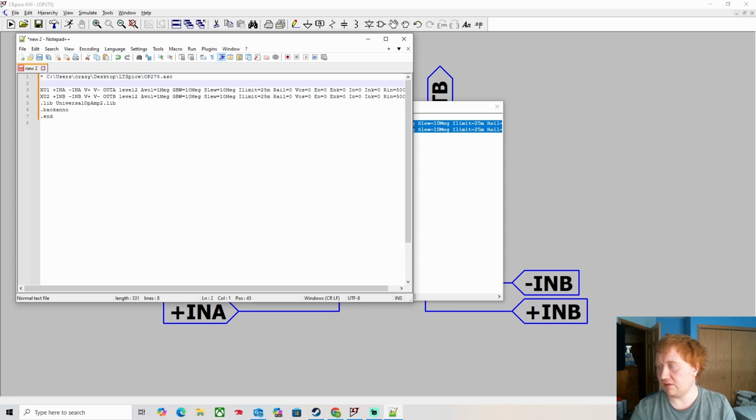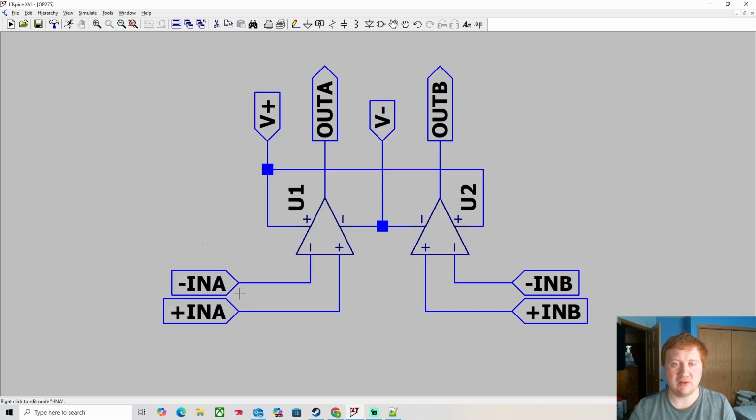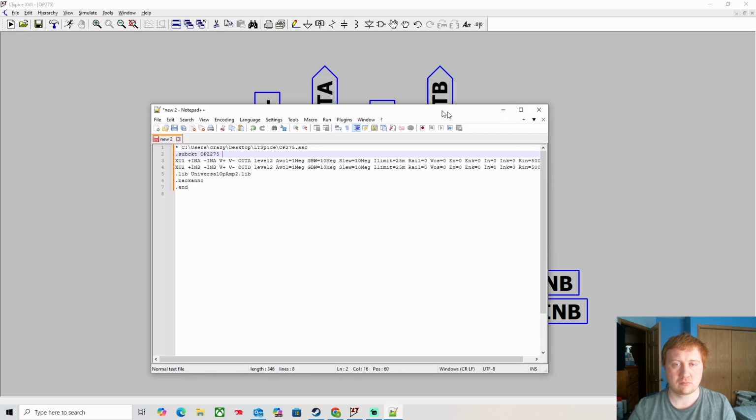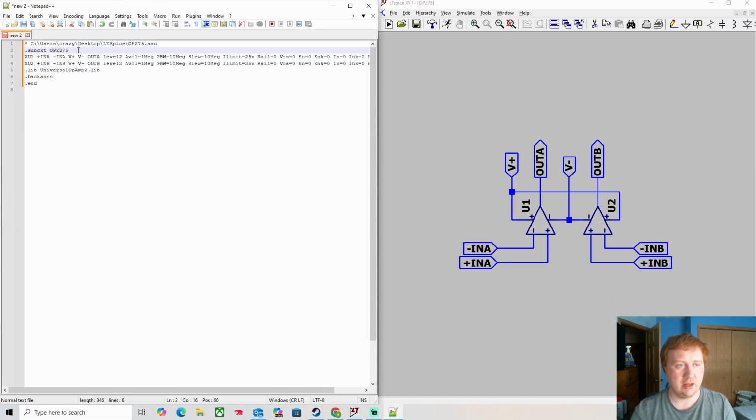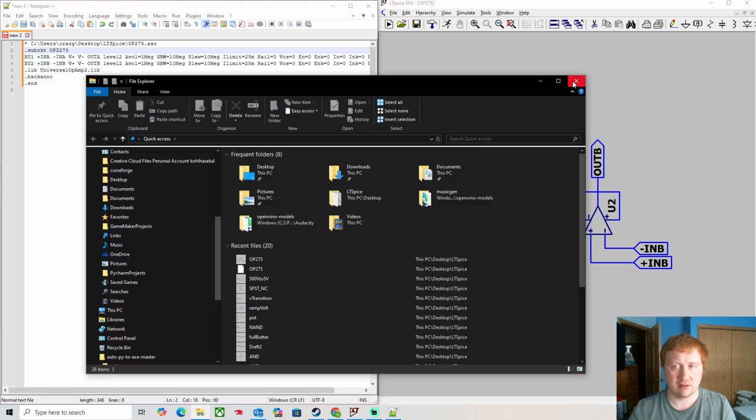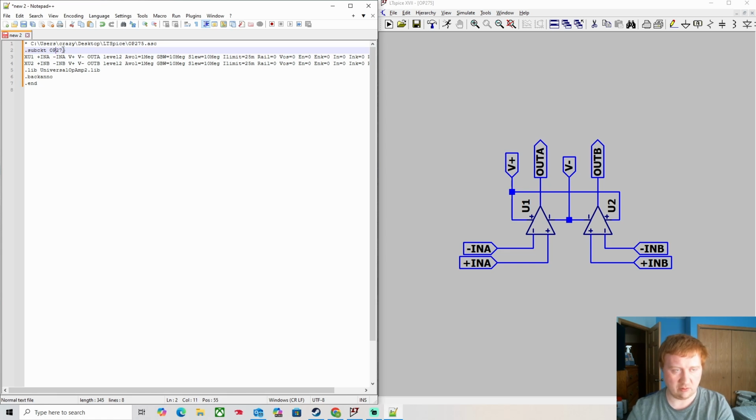So right at the beginning, you want to do .subckt, and then we're going to say OP275 because that's what we named it. And then we have to list the same names that we used for the pins. So we have to use these same names. Let's see if I can get a split screen going here. Okay, OP275. Did I say it? Hold on. No, I said OP275. It would not work if it's not the same.